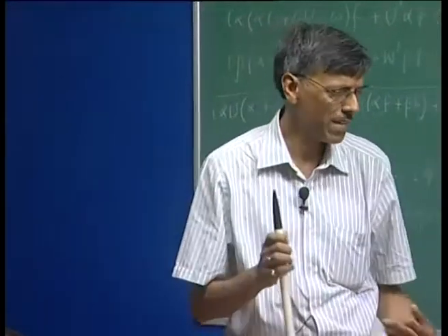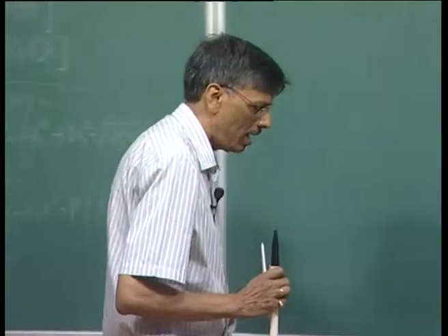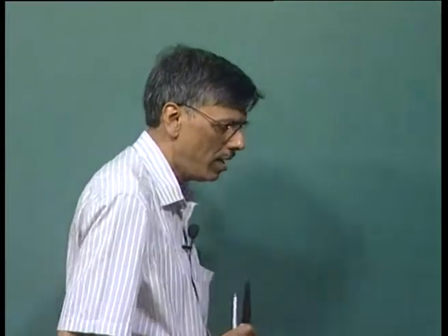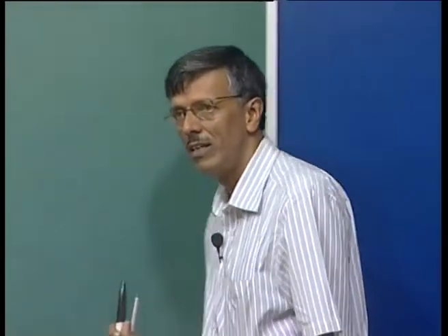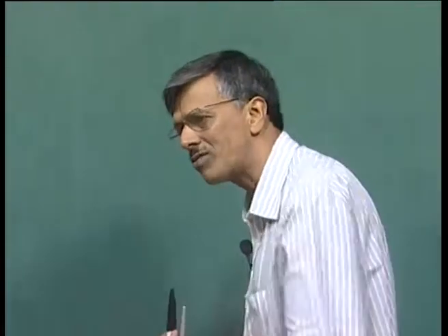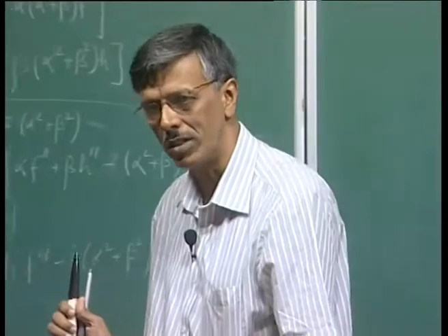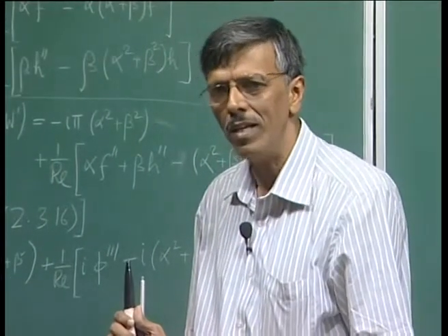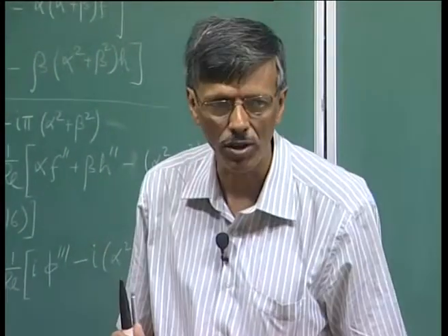So what you are seeing is that the 2D disturbance field is going to give you a more conservative estimate. It will indicate instabilities faster than the corresponding 3-dimensional disturbance field. This is what is called Squire's theorem.